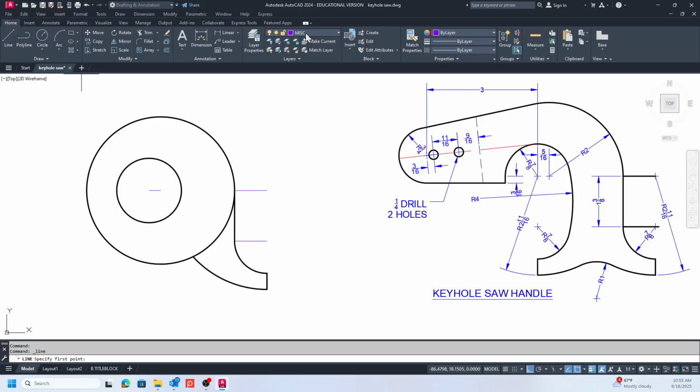So line miscellaneous from the left hand side of the 5/16 line, straight down, 1 minus 3/8, enter. Switching our properties to model, we are going to put the 2 11/16 radius in and the 7/8 radius in.